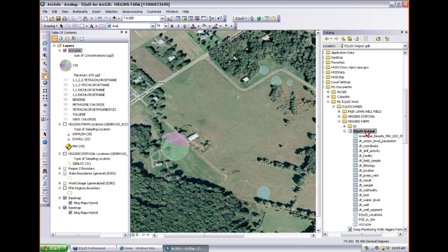You can export it to what they call a data package, which you can think of as like a zip file for GIS data. The nice thing about these data packages is it saves the symbology with the data. So it's like a zip file, but with symbols. Because in the past, you'd have to share shapefiles, which is like seven little files, and you get no symbology to go with that. So they've made it a lot nicer to share the spatial data.